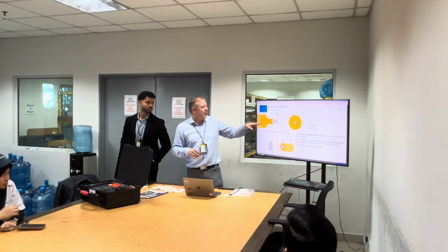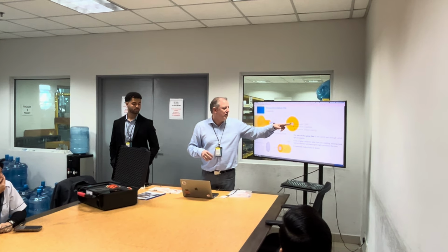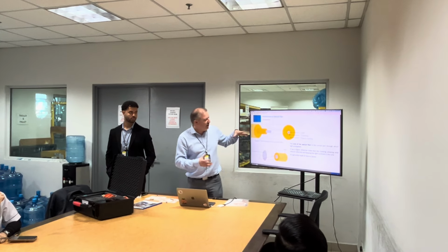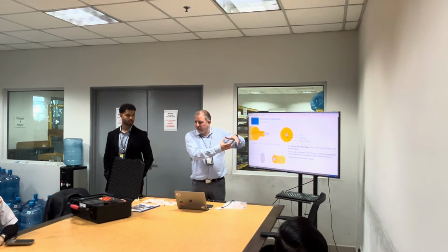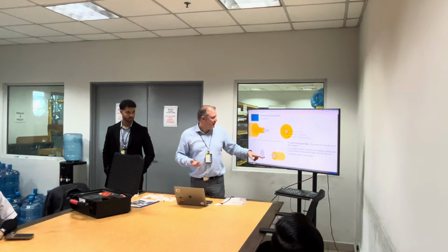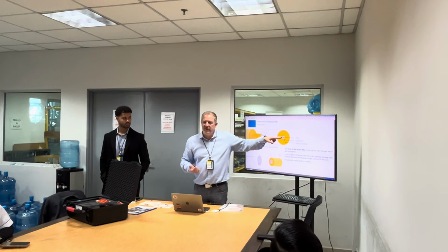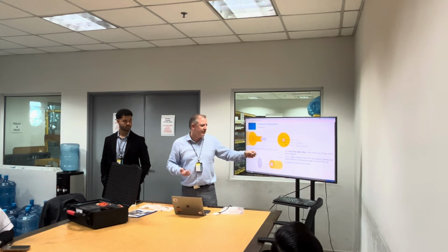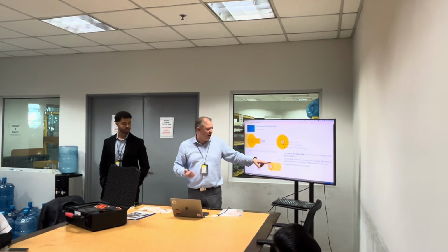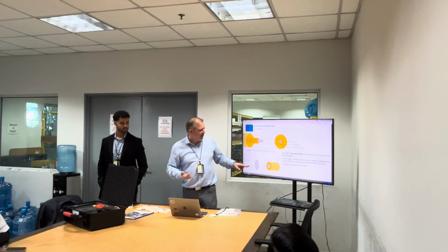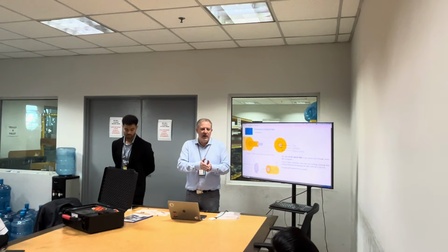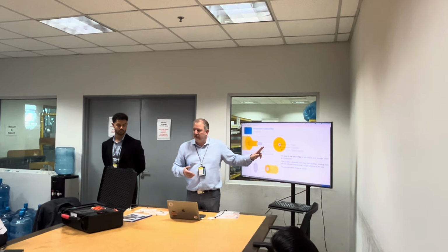So just so you know, a fiber optic is made of a core part, a cladding part, and a coating, and usually above that you even have more protections, so the fiber does not get damaged. The light is guided within the core, so the refractive index is different enough between the core and the cladding that when you send light in, it is controlled, and there's no way for the light to get out of the fiber.